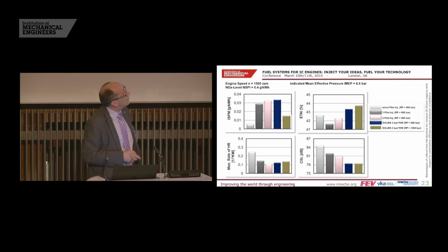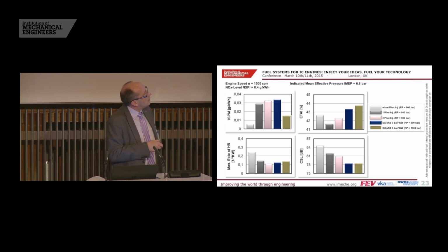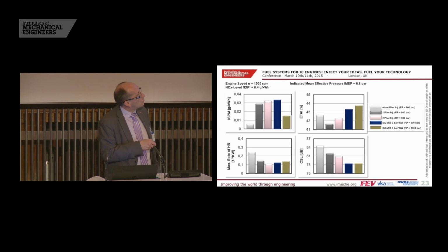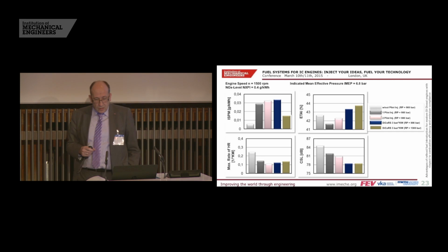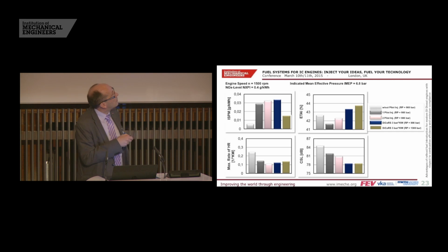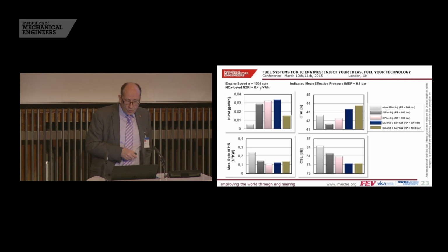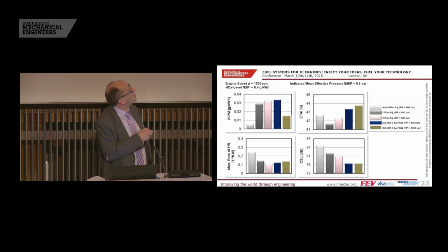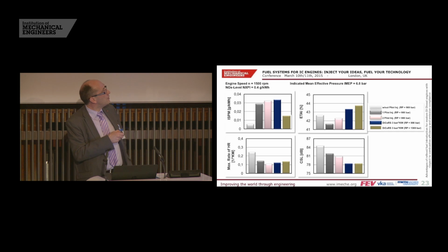Summarizing this in one chart: with software algorithms which are able to, on the basis of a combustion pressure sensor which is monitoring the combustion chamber, ensure that you have a constant degree of pressure rise. You see that it is possible to optimize to a certain extent under constant NOx emissions, like shown here, 0.4 gram per kilowatt hour at this 1500 RPM light load point. You can optimize the particulate emissions to a certain level by optimizing the combustion efficiency,